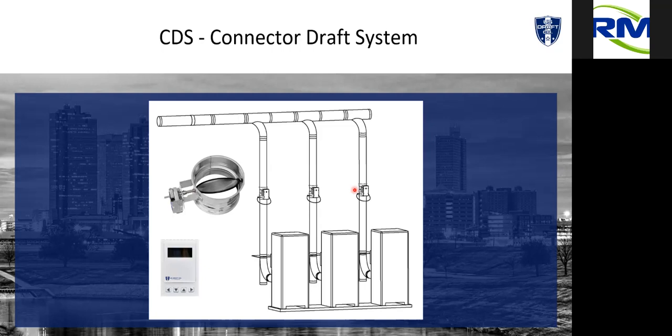And what we've done a lot of systems, and this just popped up on the screen as a question, where we'll actually set these as a positive, and then we can either naturally or mechanically size the common for a negative. Okay, so for instance, in my scenario, if I wanted to run these at a 0.05 positive, but in order to do that, I want to maintain a negative here so you don't get any spillage. Now, truth be told, these are positive shutoff dampers, so we don't really care as much if it does happen to go positive. But in order to maintain whatever we want here, this has to be more negative than your set point at all times. It's the only way to do it. Okay, so that might be naturally, or that might be using a fan. Many systems where we'll have the fan pulling this negative, and again, I'll still maintain my certain pressures here, but then I'll set these for a positive. Okay, and it really allows me the flexibility to get exactly what I want at each appliance.